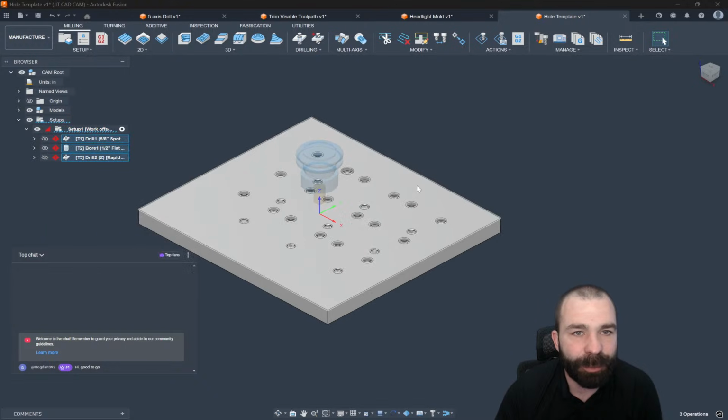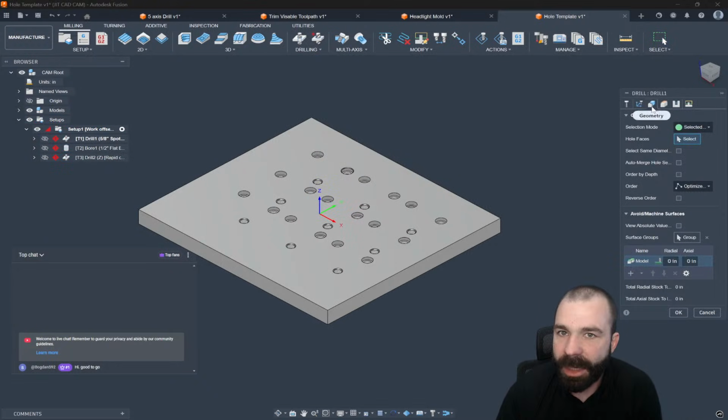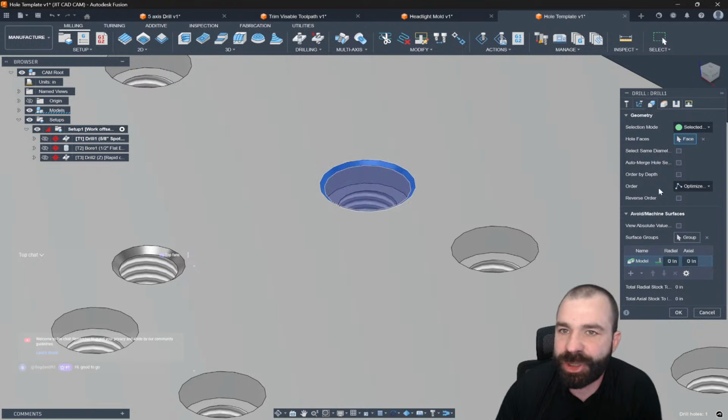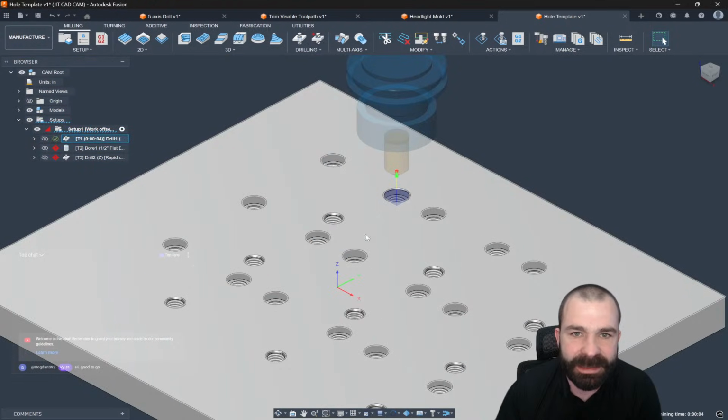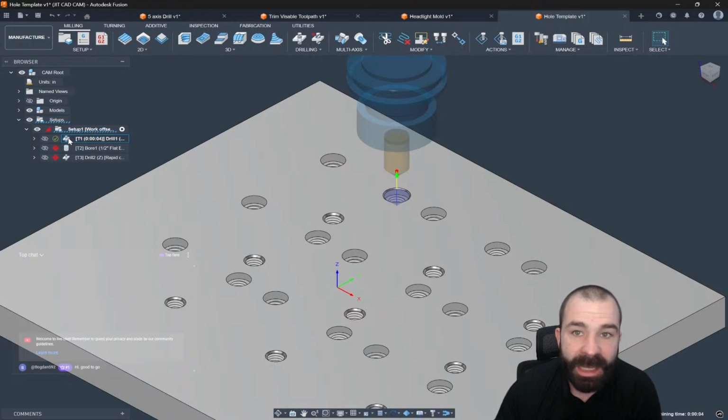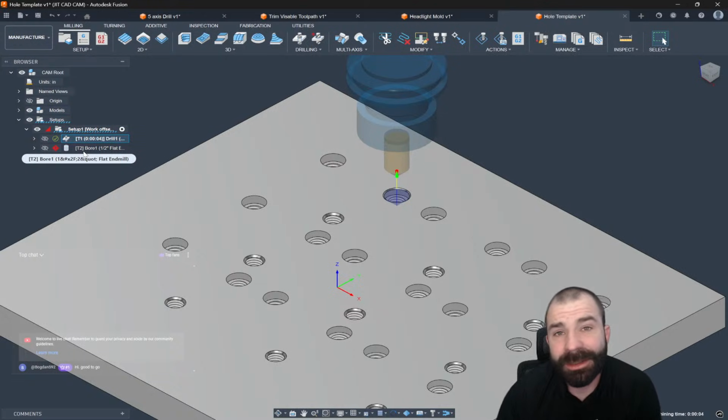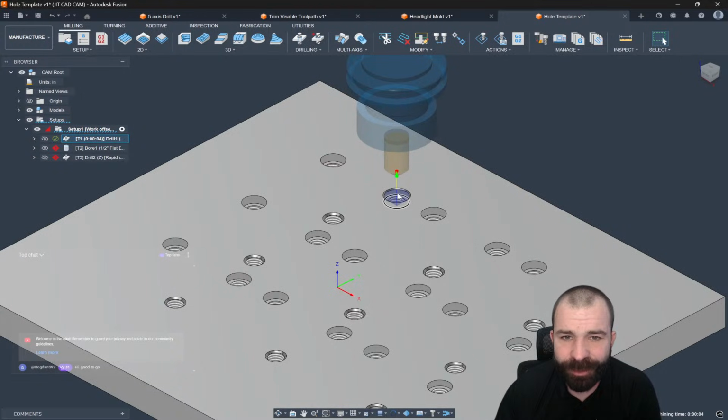So I'm going to go ahead and bring that back in. Again, we drove that off a surface originally, which is kind of strange to me that it didn't automatically pull through. Let's get our select same size diameter turned on. And in this case, we're not picking the same size diameter, and it makes sense because yours truly, like always, did something messed up, which was I failed to chamfer all of the holes. I only chamfered one of the holes, right?